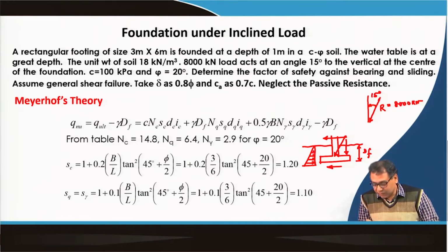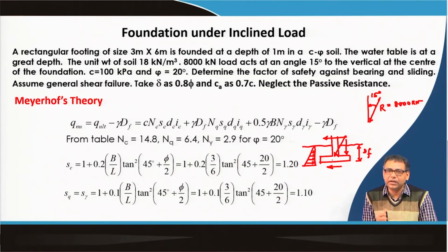So, from where will I get the resistance? I will get the passive resistance as well as resistance from the base soil, because your foundation is sliding. In retaining wall design and this type of foundation design, we generally neglect passive resistance, because if my foundation is safe without considering the passive resistance, then obviously it will be over safe if I consider it.